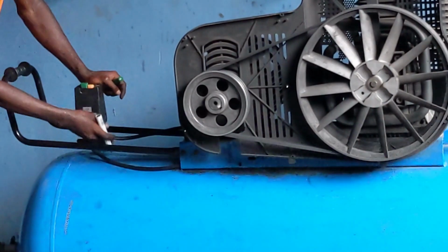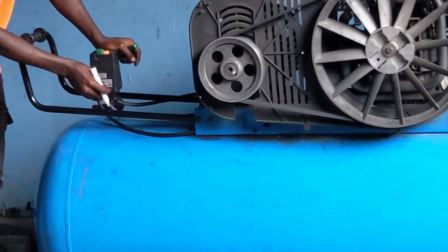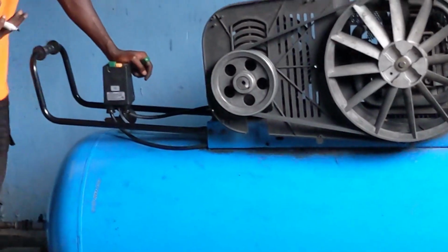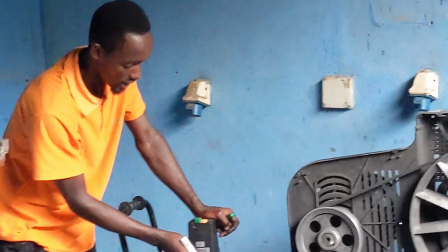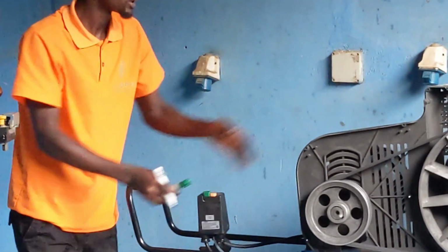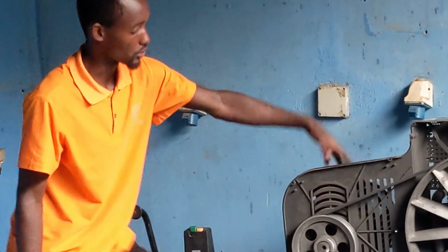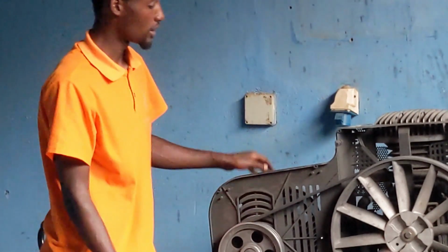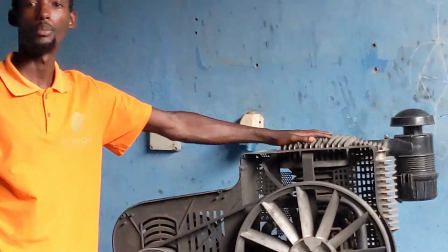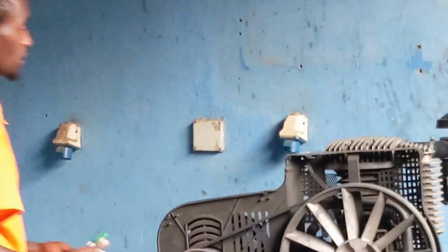So there is another control there by the air. There is a spring inside there. When the pressure inside this pilot pipe gets a higher force than the spring, it will disconnect the switch inside there to stop the operation of this electric motor. If it shuts off, it means there is no motion there, and the compressor will not run. That's how the pressure is controlled.